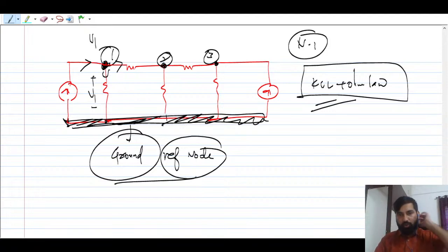So these are the things that I wanted to talk about. I'm not going to get into more detail here. Fine. So you can have the conductance matrix also. You can just write the nodal analysis and you can get the conductance matrix, right? So in nodal analysis, basically you just have to apply KCL, right? And then you can find the node voltages and all, right? And to get the node voltages, you need to know the IV relationship across each element, right?